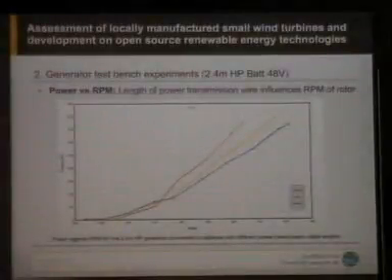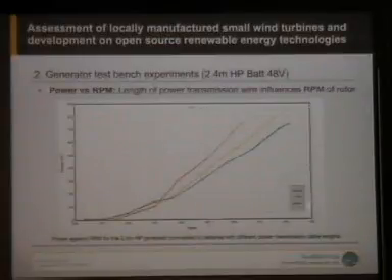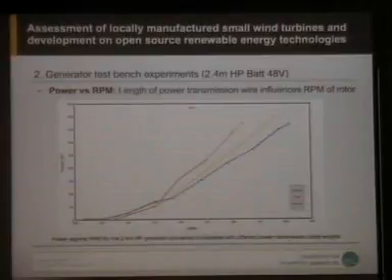These are some other tests on the same generator, using different cables of different lengths to connect to the battery. So basically adding different amounts of resistance between the generator and the batteries. This is a little bit what Hugh mentioned in the morning, where he introduced resistance into the connection in order to move to better points of operation, trying to go closer to the MPPT curve.